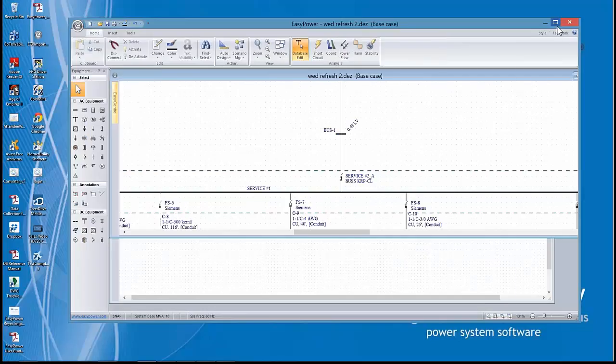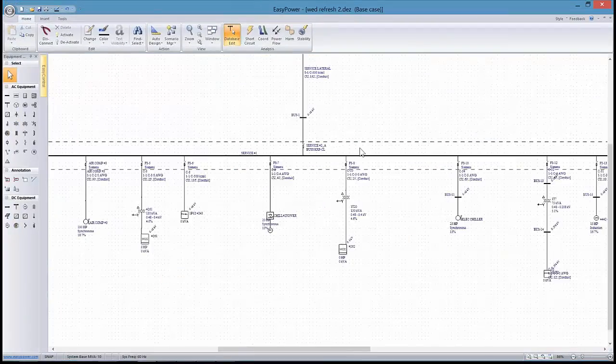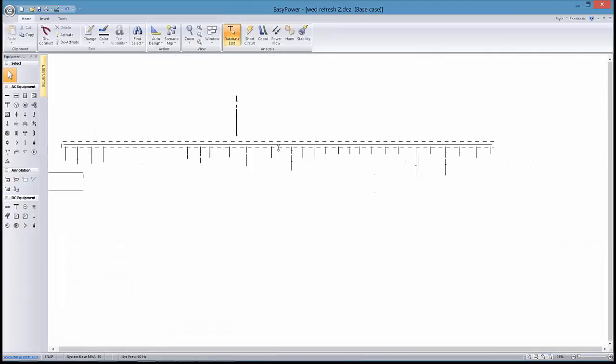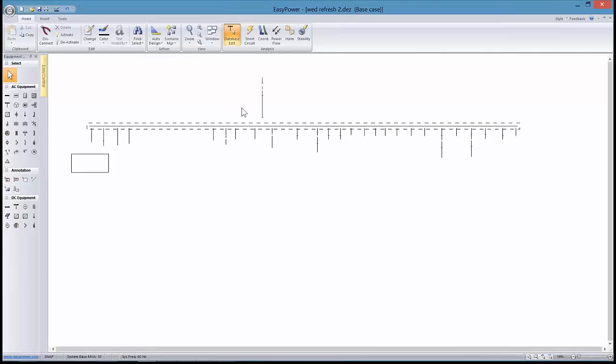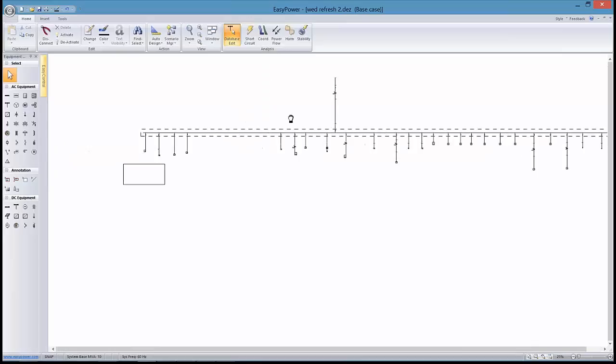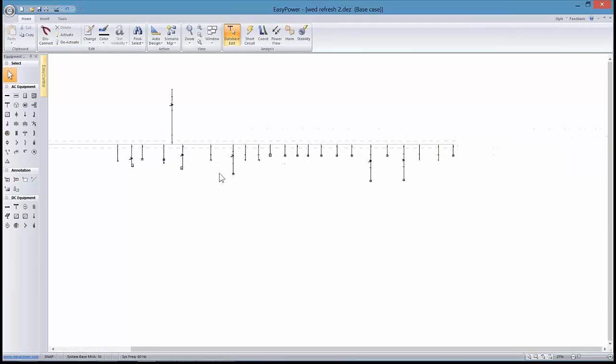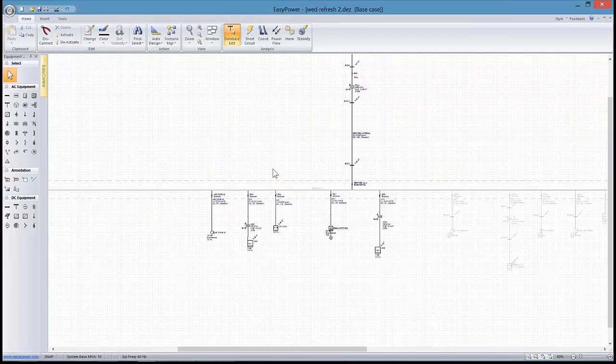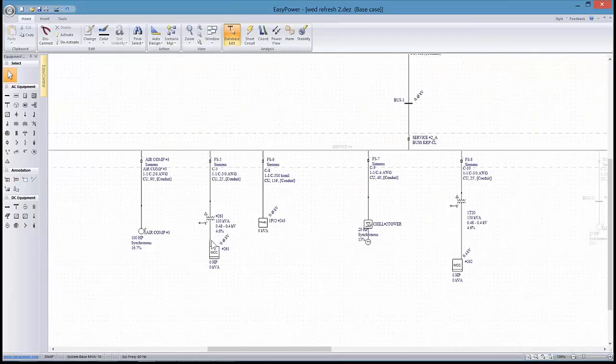As we're looking at a one-line diagram, the last thing I would recommend is doing something even this complex before you start verifying you have a handle on how to do the analysis. So what I would suggest is going in, highlighting, and disabling. If we're in the database editor, we have the ability to deactivate certain parts of the one line to limit our focus. And so as we deactivate that, we can come down now and look at specifically what's going on.